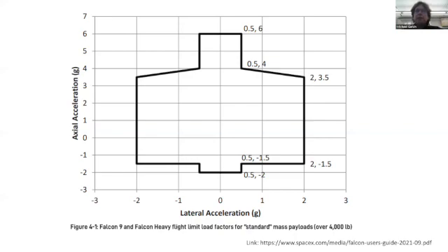And it's probably important to note that there really aren't any real static loads during a launch. The launch is a very vibratory environment. It's very dynamic, and everything's shaking and chattering. So there aren't really any boring static loads during a launch.